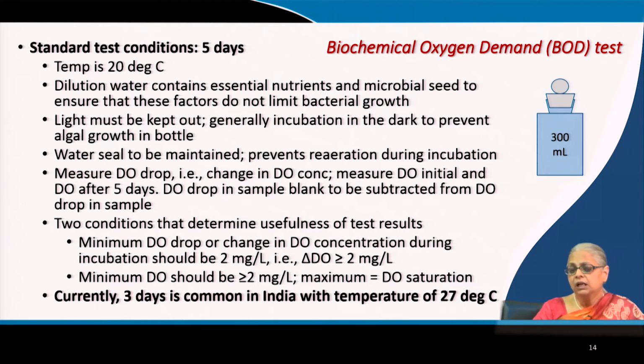Now in India, we have two issues. The temperature in the ambient environment is much higher in comparison to a country like the UK. So the temperature that the CPCB has chosen is 27 degrees centigrade, and because reaction kinetics are much higher at a higher temperature, we are using 3 days rather than 5 days to get a result.